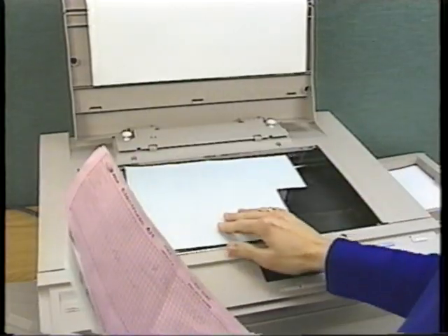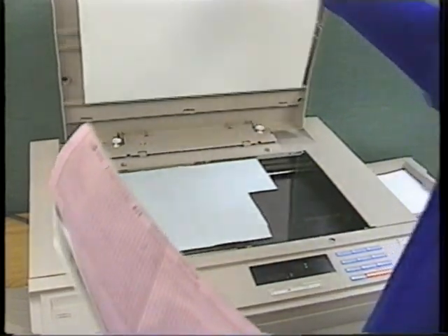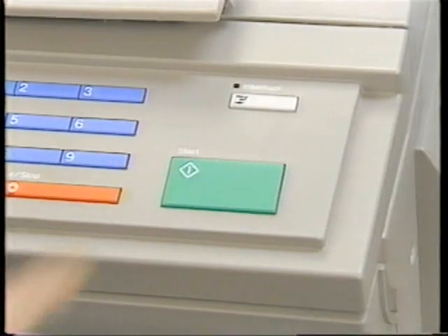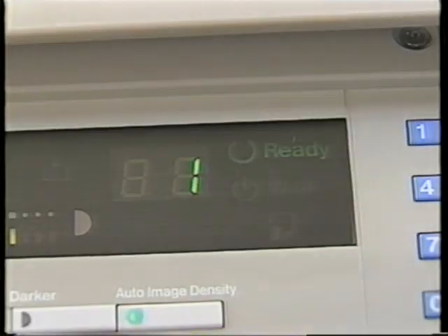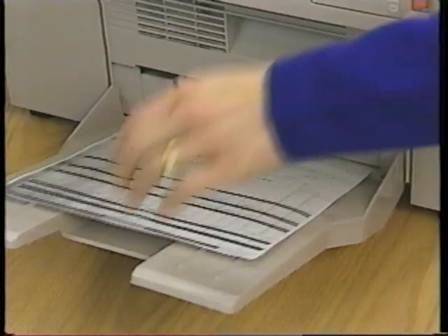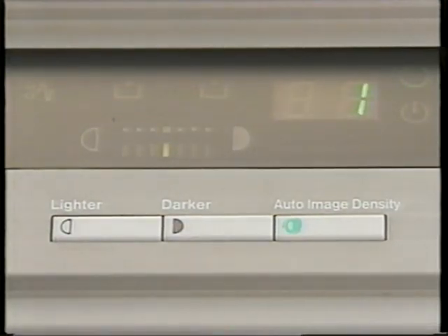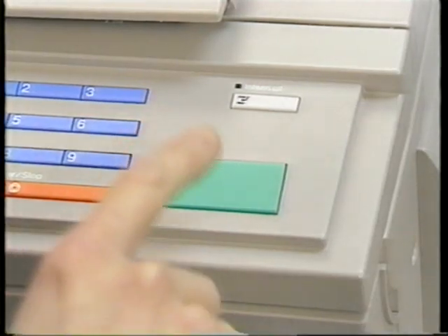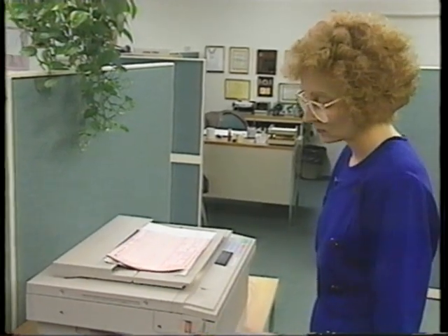This method keeps the ratio of toner to carrier balanced for an average copy, but isn't responsive enough to change image density one copy at a time. It also can't cope with the presence of toner background that can appear even with a clean original. For this level of control, the machine needs a system that responds with an immediate change in image density.